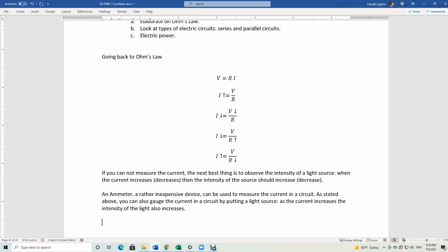Since there is no light bulb, we are not able to see a light shining. But you should understand that there is still a current in this circuit. We cannot visualize the current through the light bulb because there is no light source in there. By the way, my resistor is becoming so hot here. I gotta be careful and take out this resistor. It's so hot because this resistor is very low. I gotta put a higher resistor there, otherwise I'm gonna burn my resistor. The resistor was very hot because the current was very high.